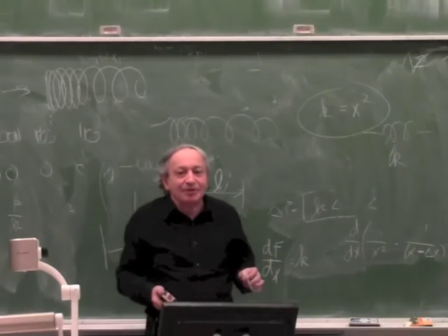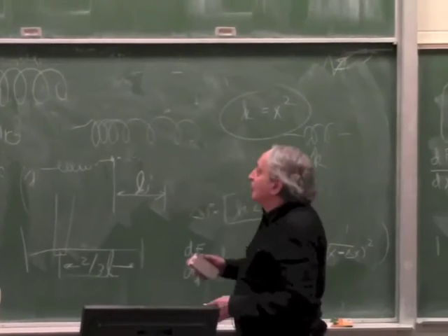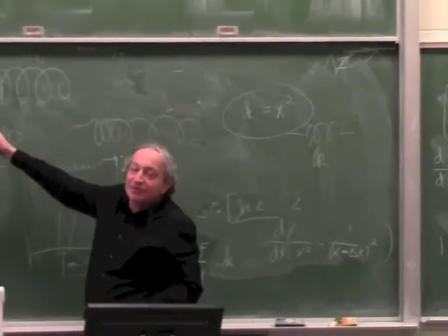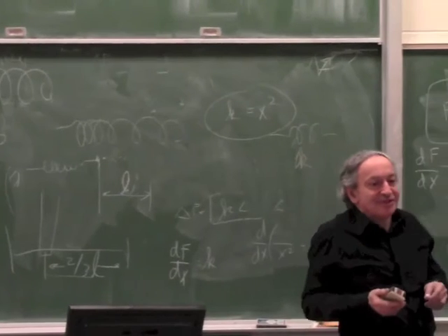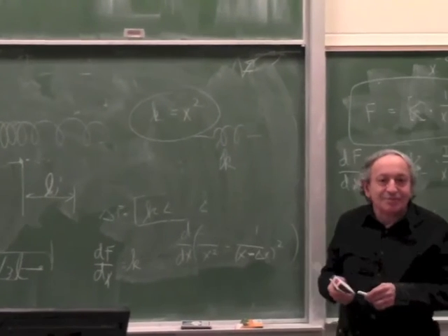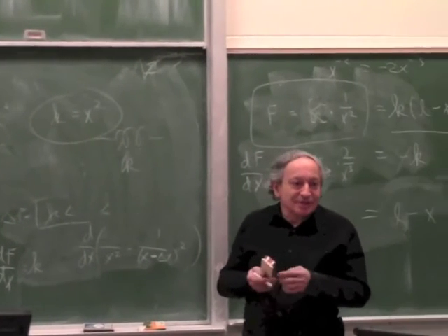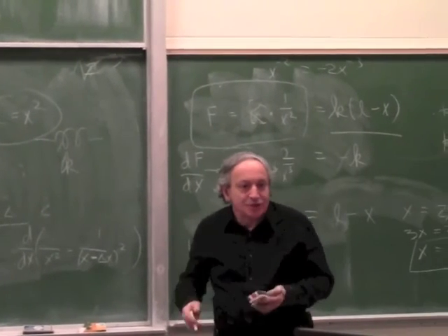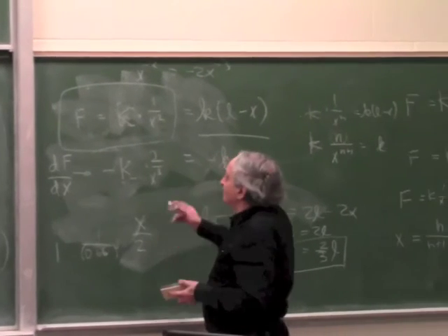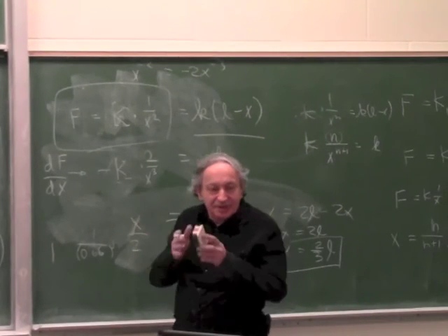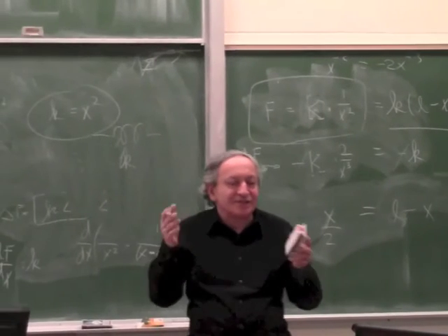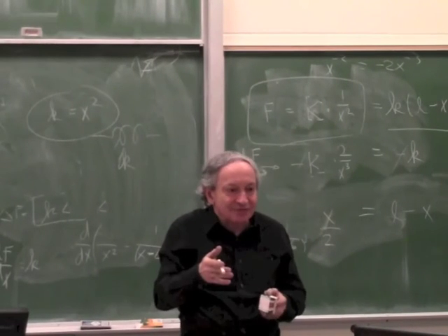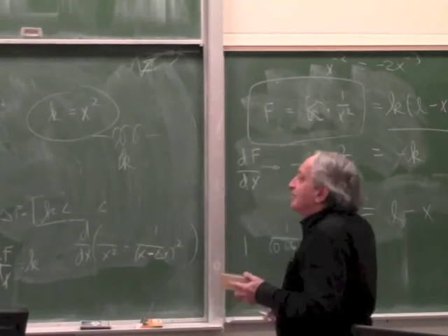So the simplest way to make a nonlinear spring is to use a compression spring wound with 1 over x or 1 over x squared spacing. There are many ways to make a nonlinear spring. It's actually very simple, so that's a very good suggestion. If you had a nonlinear spring, you can increase the range a lot. You still have nonlinearities in the servo because of saturation, but it's much better overall.